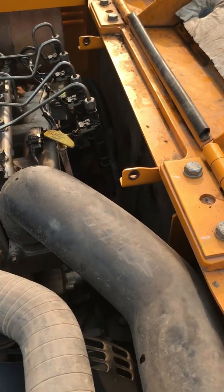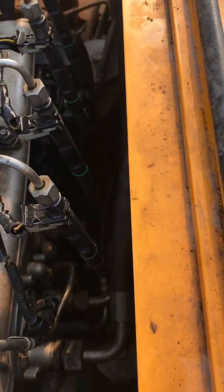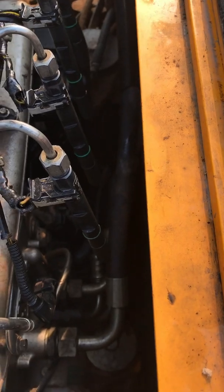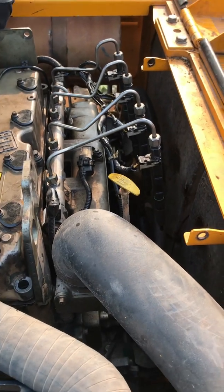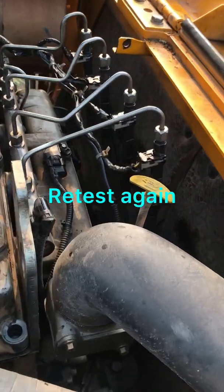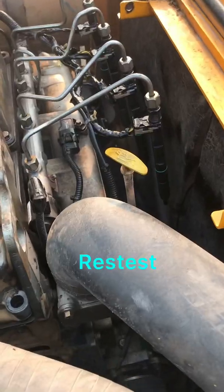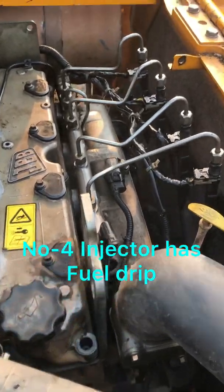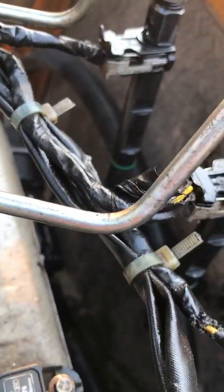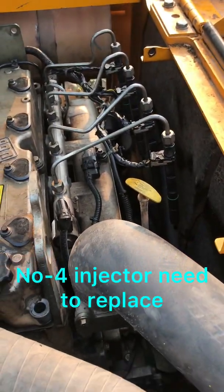Only see one injector. Only one injector. Number 2 injector. 1, 2, 3, 4. The others are not injecting. So that's why this engine cannot start. Dripping. As you can see, number 4 injector is dripping. So this cannot be used. Cannot use it. Must be replaced.